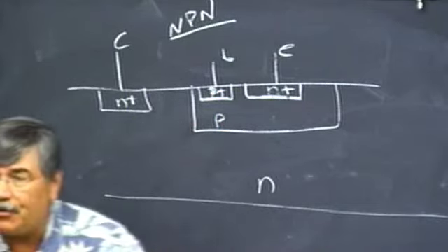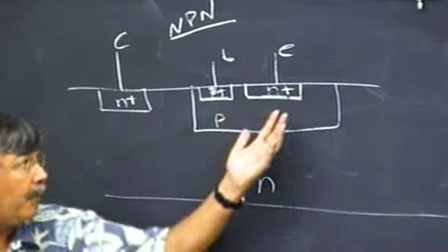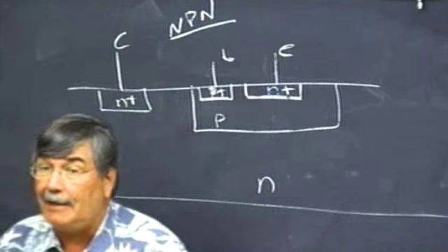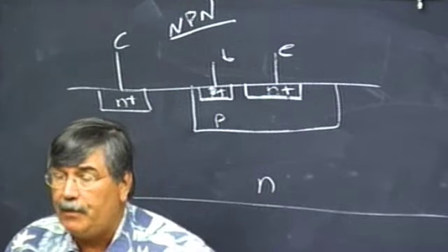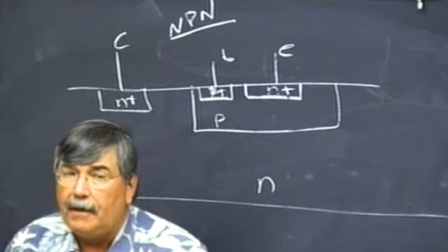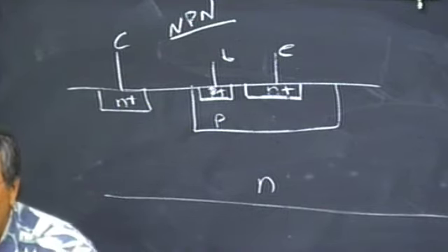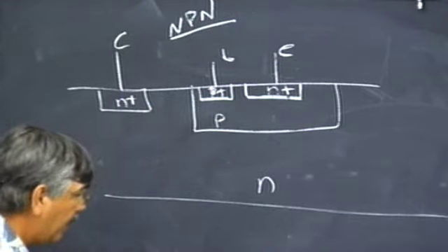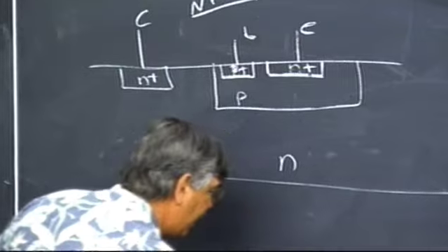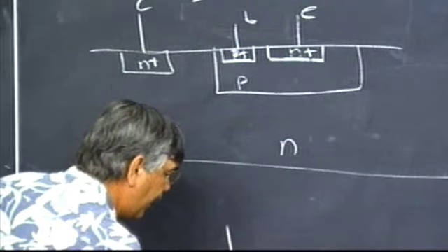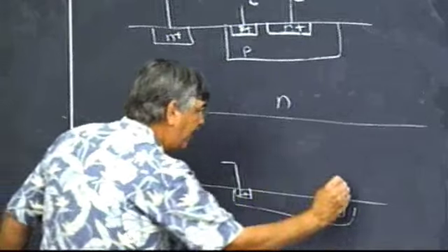One of the things that I should say in general, I mentioned that when we have very heavy doping, N+ or P+, it's like a metal. There's lots of electrons or lots of holes. That means for any field, we don't have much resistance. If that makes sense, then you must understand that if I have a lightly doped region somewhere and I put a contact over here and a contact over here, let's put P+ there and P+ there, this thing could actually be a resistor.